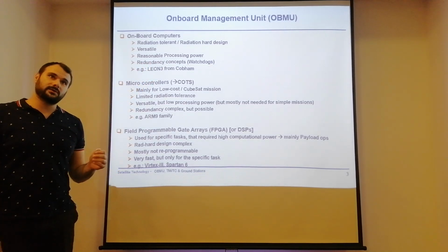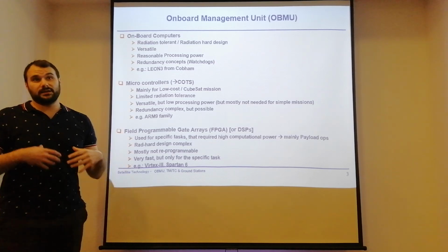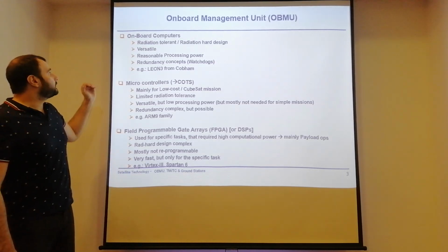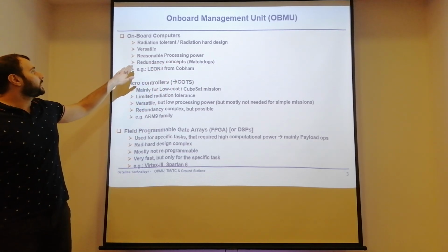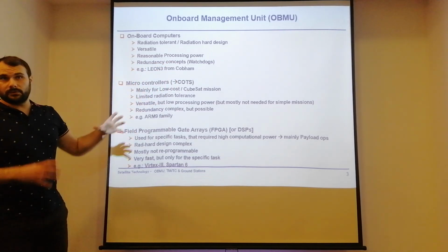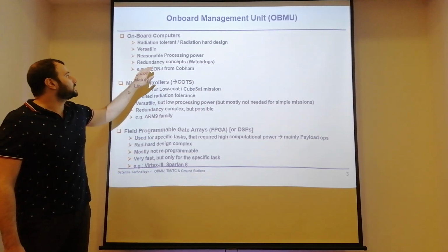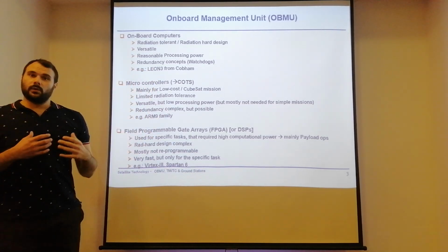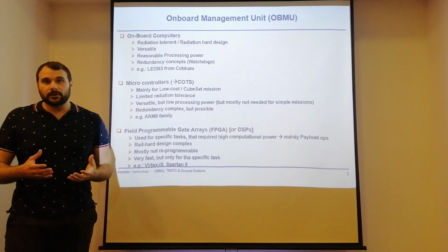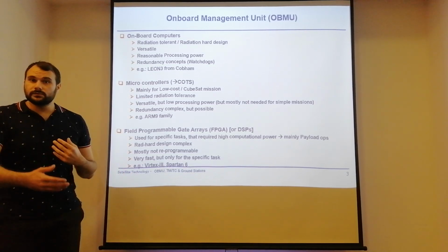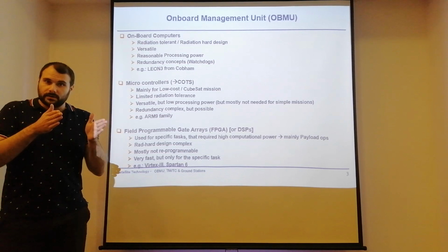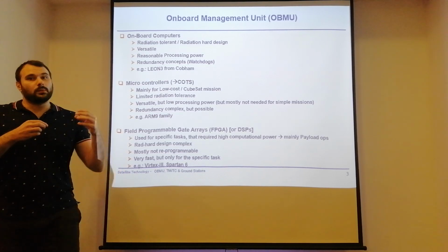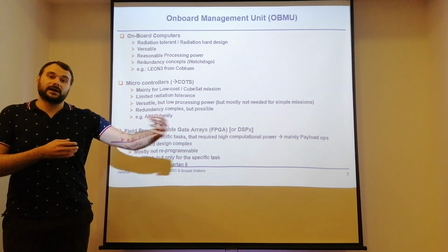That usually comes at the cost of higher mass and higher power consumption, but they are providing a reasonable processing power, and usually those space qualified onboard computers come with an already installed redundancy concept. One example is a watchdog, where your onboard computer produces a specific signal at certain times, and it self-monitors those signals if they are coming in.